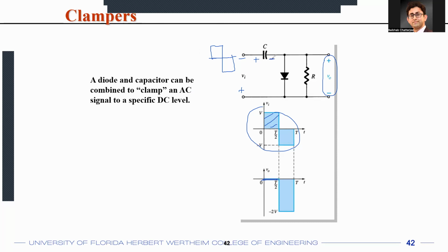because the capacitor already stored this voltage, what would happen in the negative half cycle is that you're seeing a voltage that is applied here. Let's say that maximum voltage is Vm, Vmax. Also at the same time, the capacitor has the same stored voltage Vmax because that's the property of the capacitor. It will store the voltage or it will store the charge.